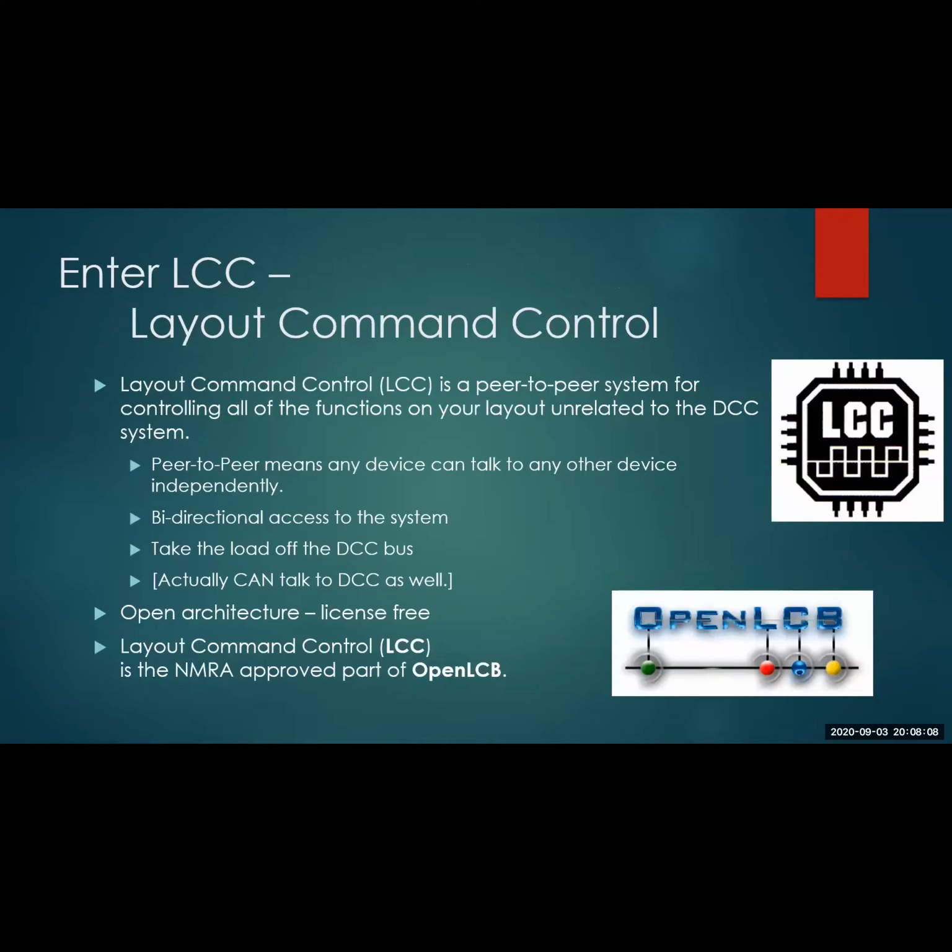So what about LCC? Why not just use one of those? Okay, so it's a separate standard. It was developed specifically for layout control. It's a peer-to-peer system. You do not need a computer to run it. You can set it up such that you have all these nodes around your layout and they just go off and run. Any device can talk to any other device. It's all bidirectional. Every device can listen to any other command from anything else.